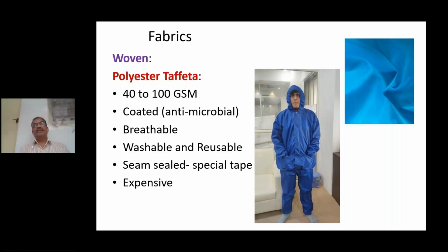Since we do a coating, this coverall is not recommended for more than 10 washes. Even practically, people recommend it only for 10 washes, because beyond that the coating slowly erodes away and it becomes ordinary taffeta fabric where the filtration will not be there. That's why it is recommended only up to 10 washes. But in this also we can go for seam sealing. Since the antimicrobial coating is done on the fabric, on the coating we can do the seam sealing for extra protection. And this type of coveralls is also sold in the market.